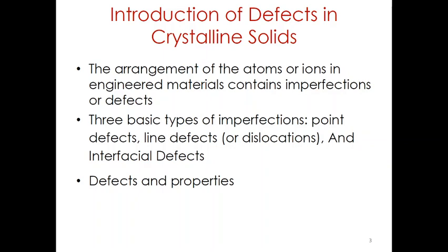In many applications, the presence of such defects actually is useful. There are a few applications though where we will strive to minimize a particular type of defect. For example, defects known as dislocations are useful in increasing the strength of metals and alloys. However, in single crystal silicon used for manufacturing of computer chips, the presence of dislocations is highly undesirable. Often, the defects are created intentionally to produce a desired set of electronic, magnetic, optical, and mechanical properties.